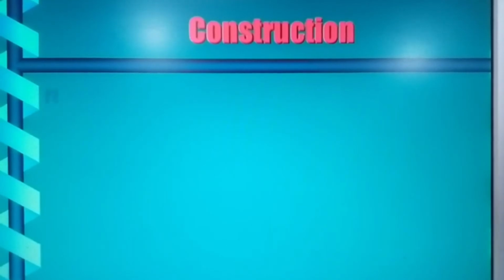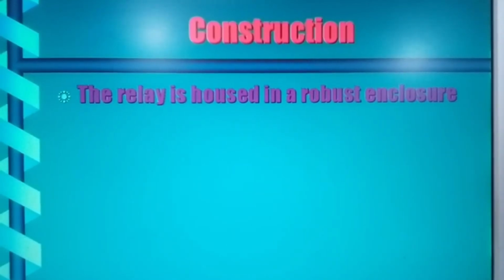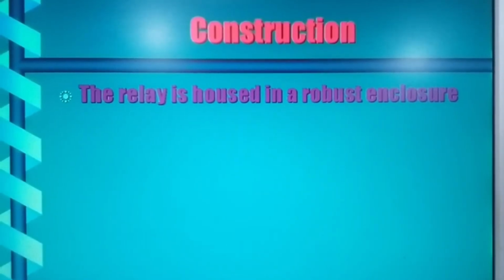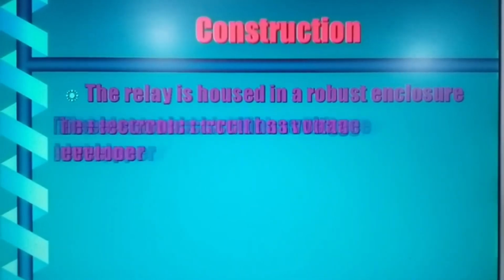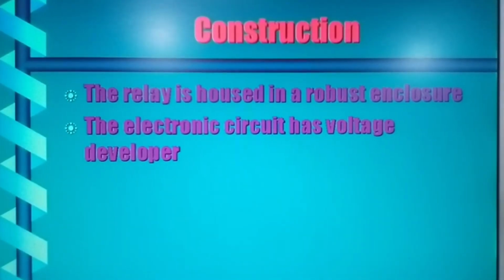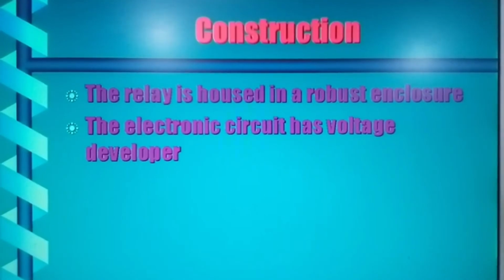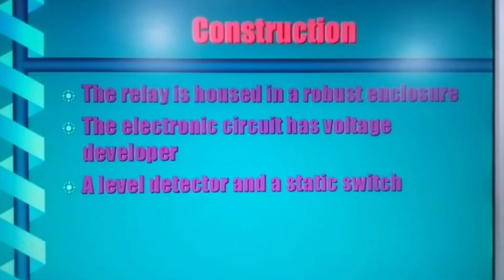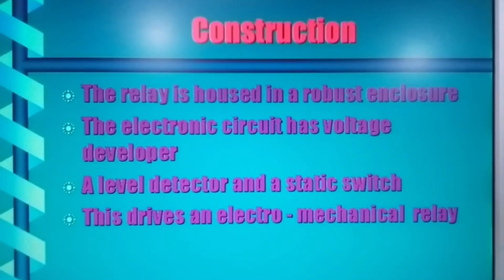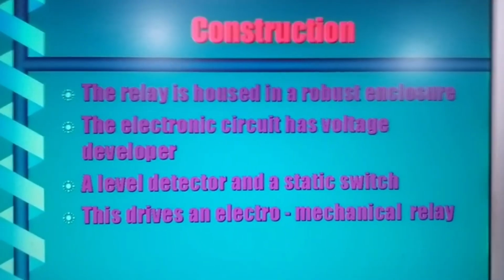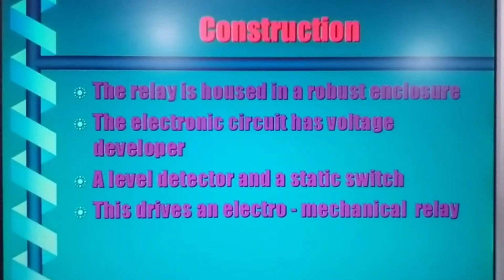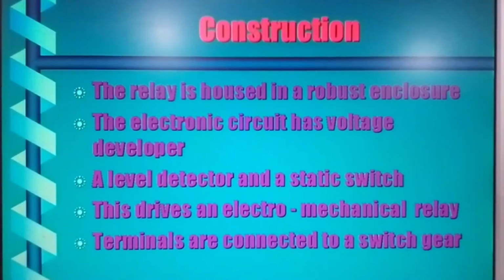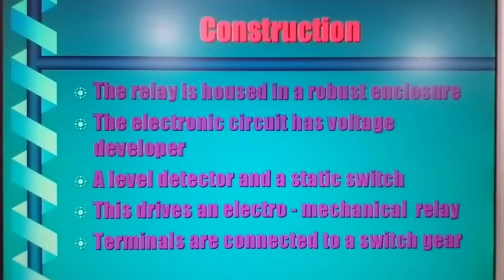Construction. The relay is housed in a robust enclosure. The electronic circuit has a voltage developer, a level detector and a static switch. This drives an electromechanical relay. Terminals are connected to a switchgear.